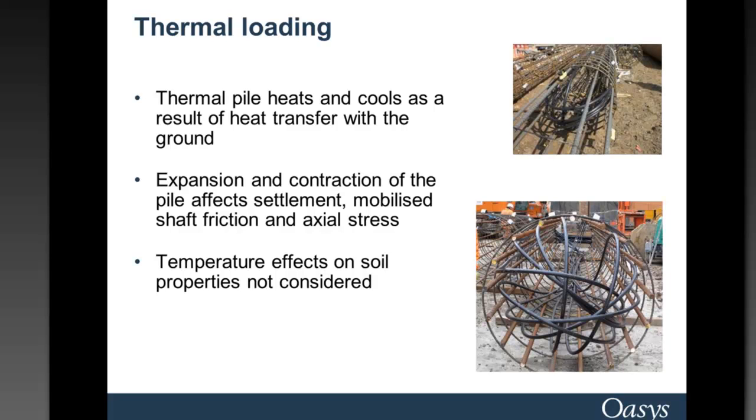That seems to be another topic that's receiving a lot of research interest at the minute, and it hasn't been overly conclusive just yet, the actual temperature effects on soil properties, so those haven't been included in the program, but the axial expansion and contraction and the effect of that on the shear, the mobilized shaft friction, has been included in the program.